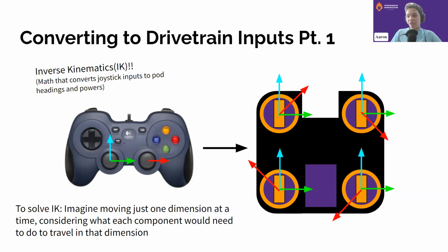If you're going to go with coaxial, I'd say 4-pod is probably the best because it gives you a relatively similar amount of power to a 2-pod as well, while also having a lot of ground clearance with the coaxial swerve. But 4-pod differential swerve is also a really good option if you're doing 4. I'd say it just depends heavily on the game type, really.